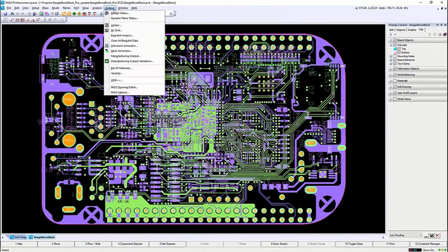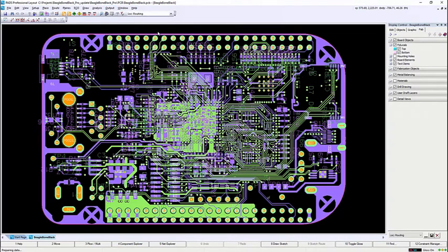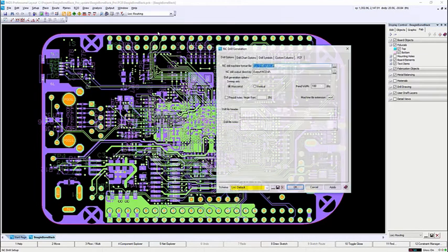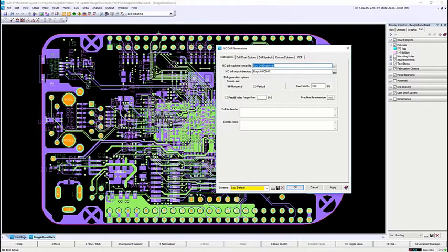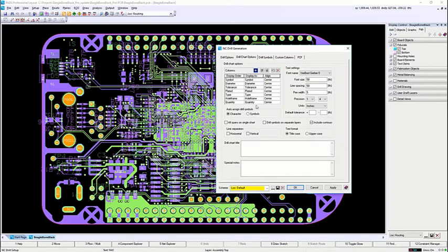Drawings and panels are used to organize data, but in order to manufacture a design, files of a different nature are required, ones with detailed information to guide fab engineers and machines to build the desired product. There are several easy output file generators within the PADSPro toolset: NC drill charts, Gerber, and ODB++ files.